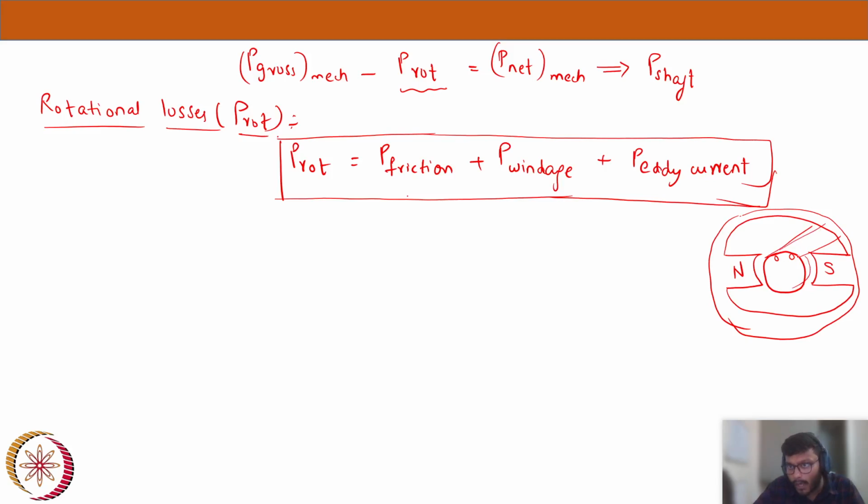This is the cross-sectional view, and this is the body of the rotor. Let's say this entire body is made up of solid iron. The rotor body is moving under a particular magnetic field. Take any closed path on the surface of this rotor body, and it will see maximum flux at one instant and zero flux at another. Whenever the air gap is minimum, it will see maximum flux, and whenever the air gap is maximum, it will see zero flux.